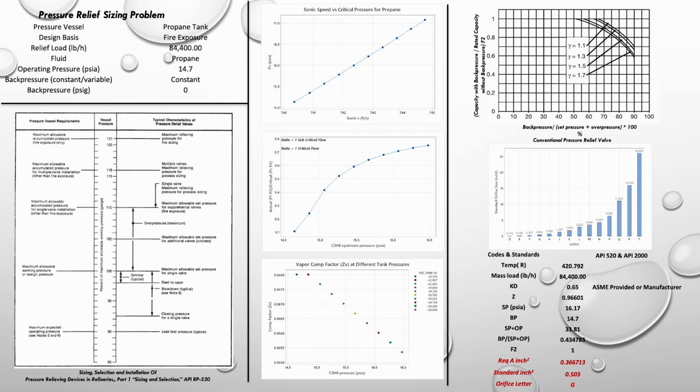So what's going to matter for how much mass? It's going to be density multiplied by area multiplied by velocity. So V is constant. You cannot increase the sonic velocity, and the only thing left is the area, which is the orifice area itself. Compressibility factor, of course, most likely you're going to deal with non-ideal behavior. Nothing is ideal. That's why you call it ideal.